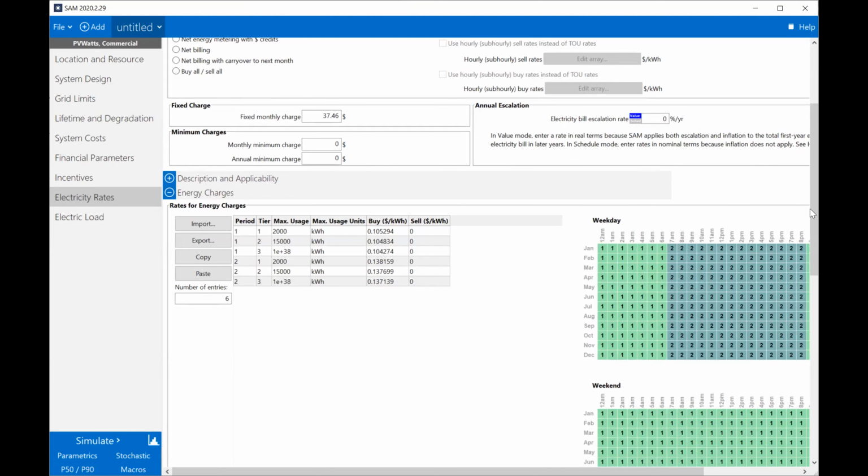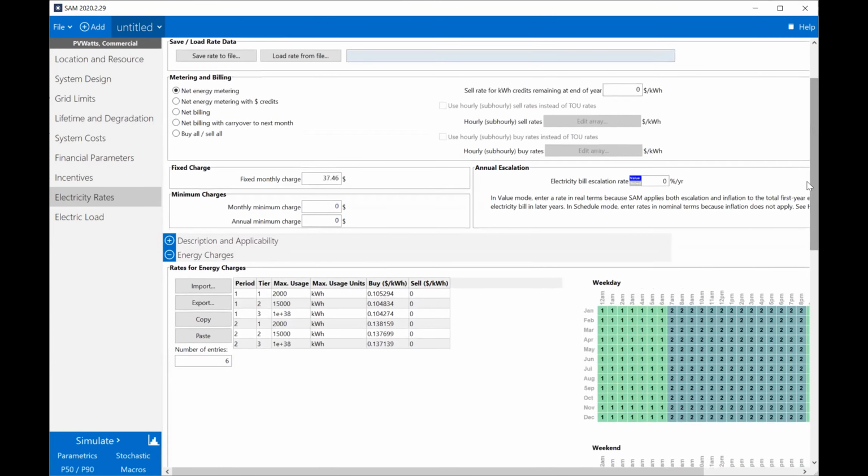John, go ahead. Eric, just a quick side note. Sometimes people think, well, why demand charges? I don't know that we've ever discussed why they exist. It's basically the idea that the utility has to build the infrastructure, the wires, the transformers, to meet your maximum demand at any one point in time. And so, if you have a real high spike that only occurs for a short period of time, it's wasting a lot of additional cost overbuilding that infrastructure. So just FYI. Yeah, thanks, Eric.